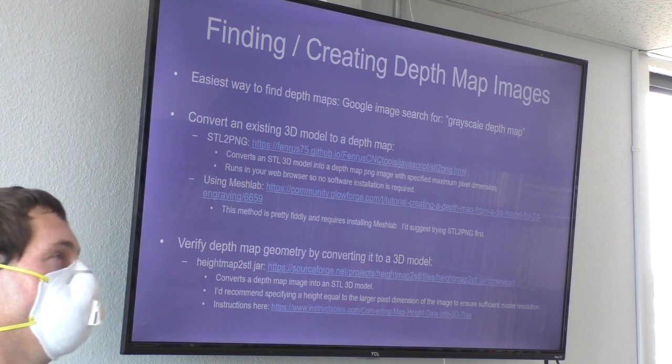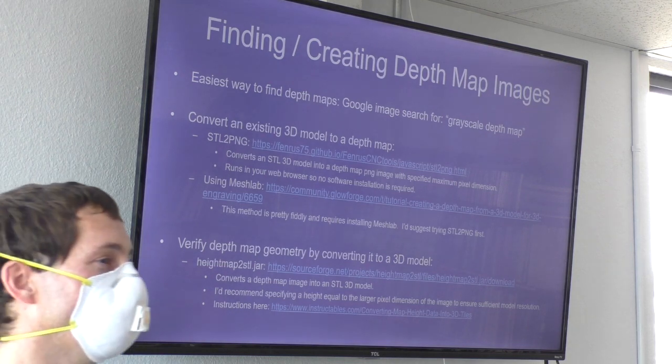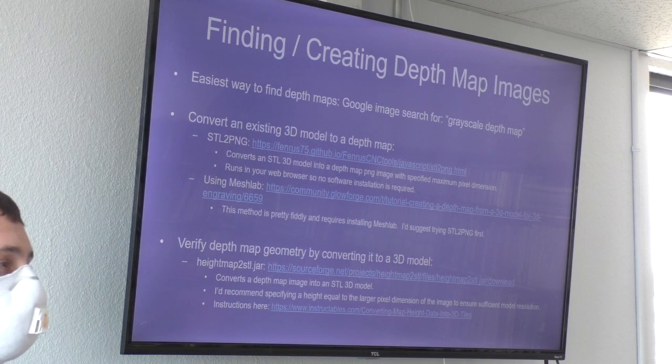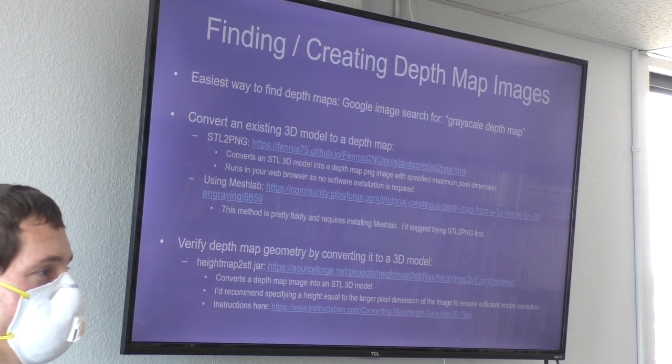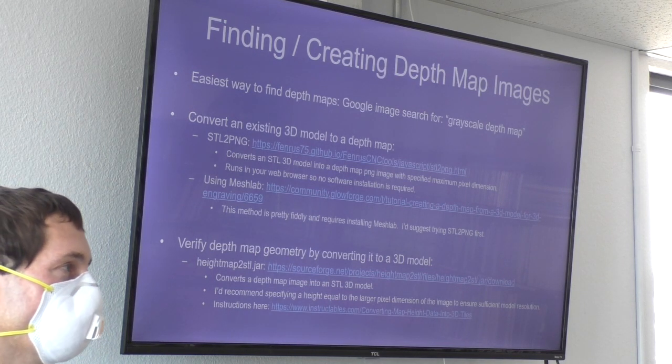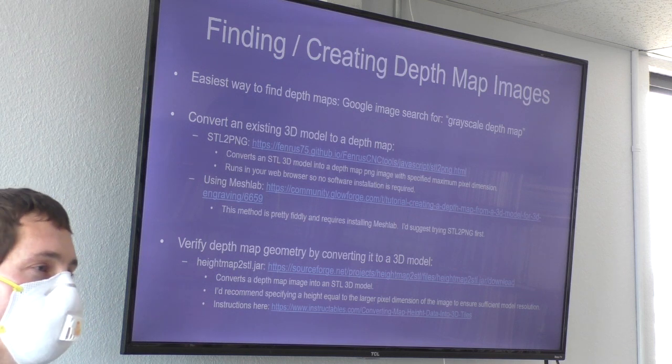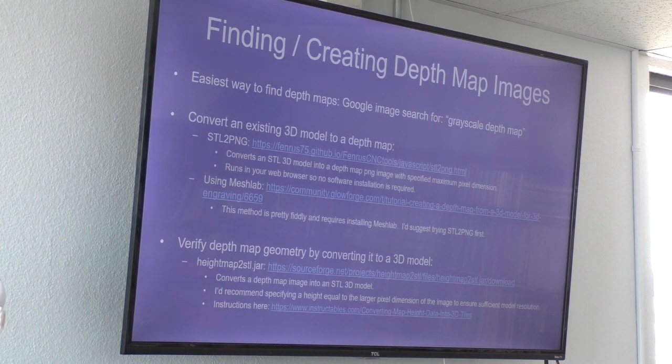The problem is that there's some general 3D models that were just like a physical object that somebody had 3D scanned and made it a great depth map image. But the problem there is that that physical object had significant depth to it, several inches, say. But when you engrave it, you're only going to get 3 millimeters if you use the 37% or 5.6 for the full range. So it's really thin. So if you try and burn that, it's going to look like basically a flat plane.